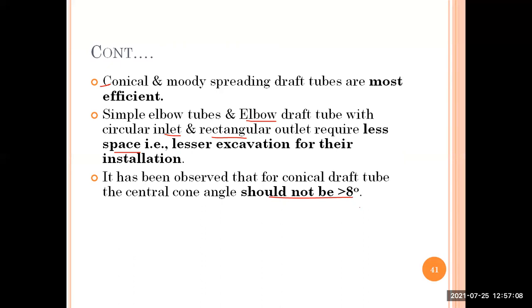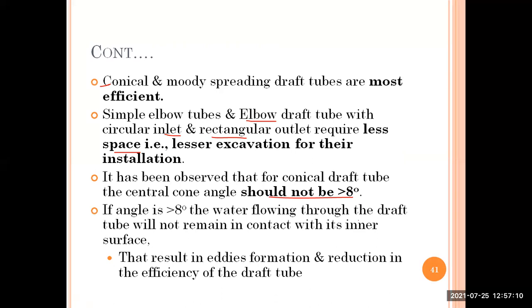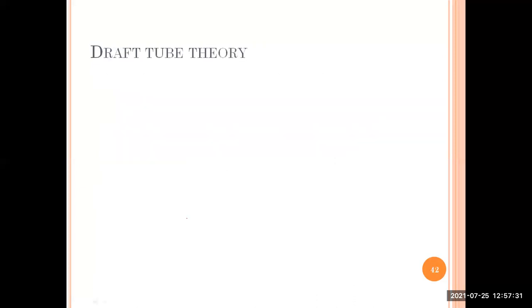Okay, so there may be an erosion, the pressure will be high, and due to that eddies are going to form, and also because of that the efficiency will reduce. So if the angle is greater than 80 degrees, it will reduce the efficiency of the turbine.